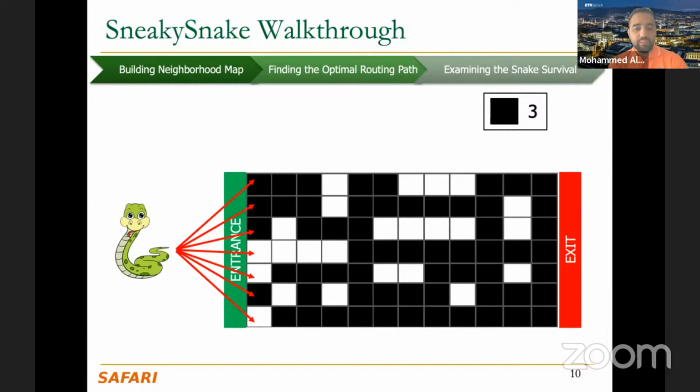It's very similar to the single net routing problem. In each row, you detect how many steps you can go further. So you find here 0 steps because you start with an obstacle or a module, then you cannot pass. So here you cannot. Here you can move 4 steps forward because your goal is always to go from left to the right. So you want to go as far as possible in each row. That is a greedy choice to get the shortest path. Because if there are no obstacles at all, then you just walk in a single row and that's it. You solve the problem.